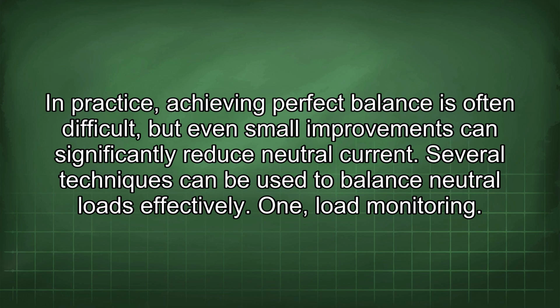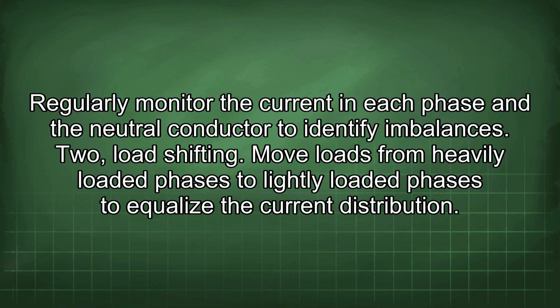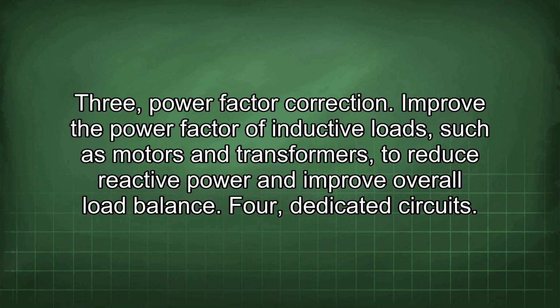1. Load monitoring. Regularly monitor the current in each phase and the neutral conductor to identify imbalances. 2. Load shifting. Move loads from heavily loaded phases to lightly loaded phases to equalize the current distribution. 3. Power factor correction. Improve the power factor of inductive loads, such as motors and transformers, to reduce reactive power and improve overall load balance.